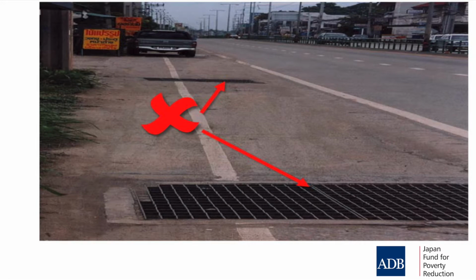This is a little bit more of a minor issue, but again, a nice separated lane, but we have objects in the lane. These are okay now because they're flush with the road surface, but as this road wears and it needs maintenance, these areas will be the first to break up, to crack up.